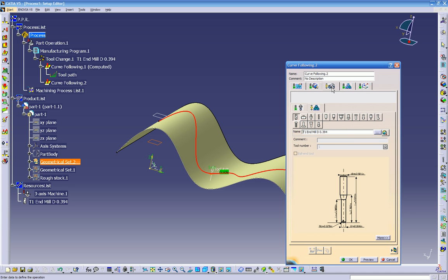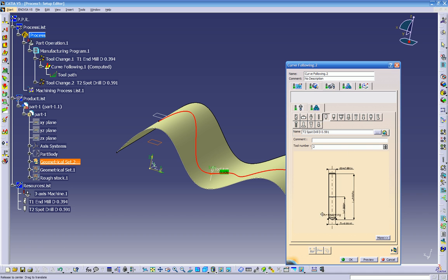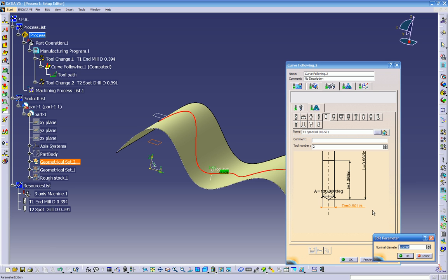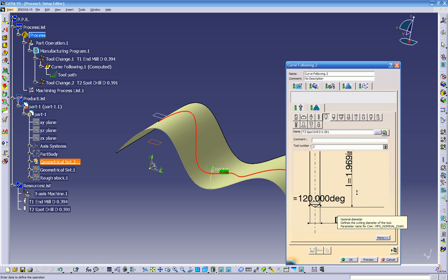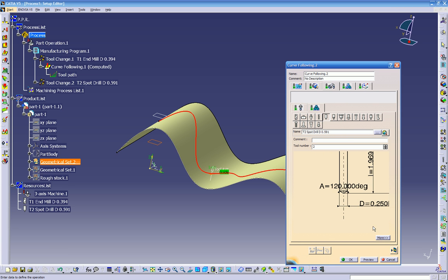And usually when I scribe the part, I usually use a sharp point. And let's use something with a sharp point, like a center drill or like a scribe tool. Let's use this just for temporary. To scribe it, it doesn't really matter in our case right now because this is not a finished part. So I'm going to make this a little smaller.